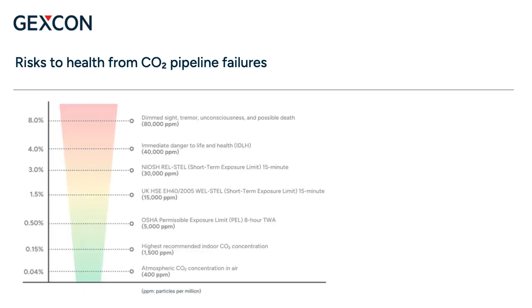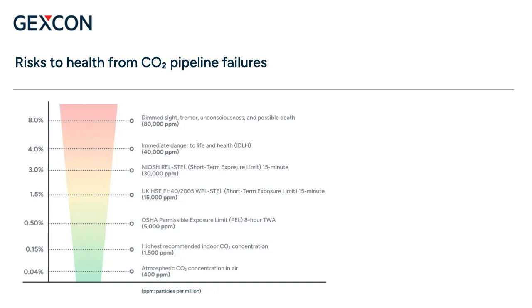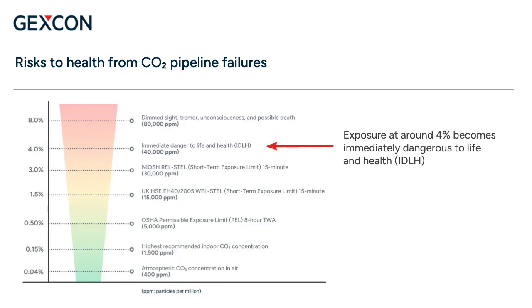Prolonged exposure to CO2 concentrations above 0.5% in volume, which is the OSHA permissible exposure limit, can result in symptoms such as headaches, dizziness, and nausea. At concentrations around 4% in volume, CO2 becomes immediately dangerous to life and health, which is a concentration typically known as IDLH concentration.